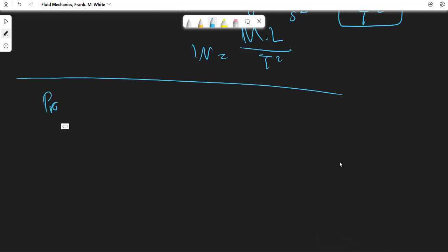Properties of velocity field. In a given flow situation, the determination by experiment or theory of the properties of the fluid as a function of position and time is considered to be the solution to the problem. In almost all cases, the emphasis is on the space-time distribution of the fluid properties. One rarely keeps track of the actual fate of specific fluid particles. This treatment of properties as continuum field functions distinguishes fluid mechanics from solid mechanics, where we are more likely to be interested in the trajectories of individual particles of the system.